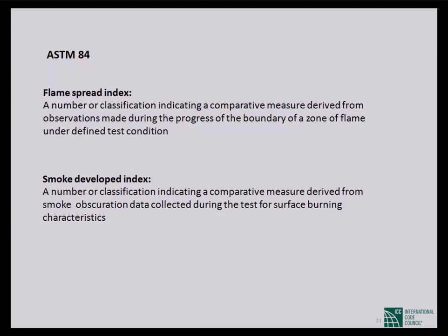You give a relative measurement of the transparency of the smoke, and it will give you an index value that gives you an understanding of how much smoke is generated by any material, but it does not measure the toxicity. It measures the density of the smoke only.